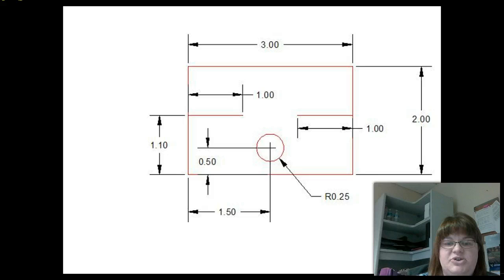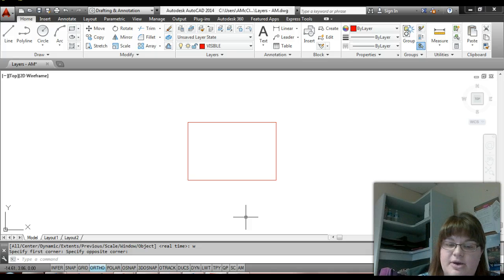So the next thing I need to do when looking at that front view, I can put in the circle as well as those 2 lines. So I know I'm going to do the circle first. Its radius is 0.25 and it's located halfway left to right and then up a ½ inch. So there's lots of different ways to do this. I'm going to go ahead and put my circle here at the midpoint of this left to right and then come back in a second and move it up.